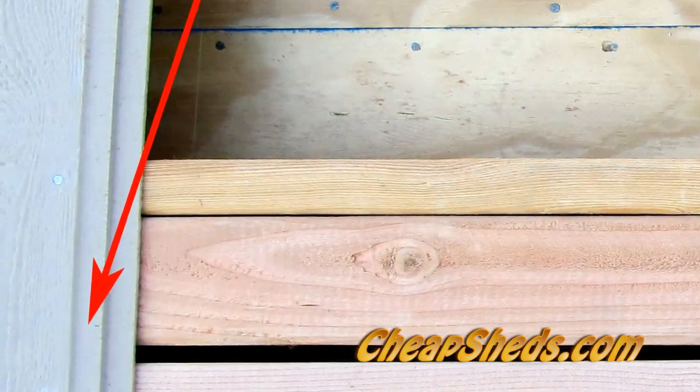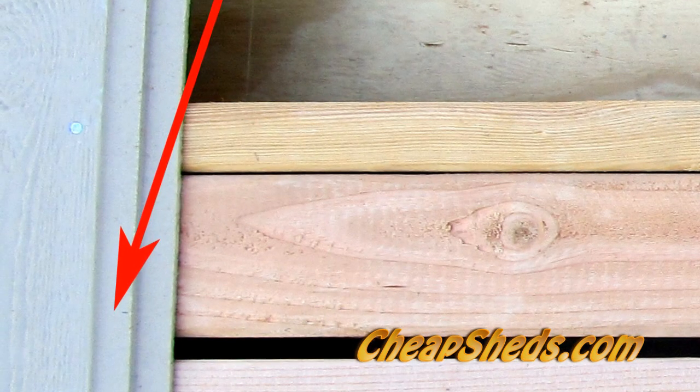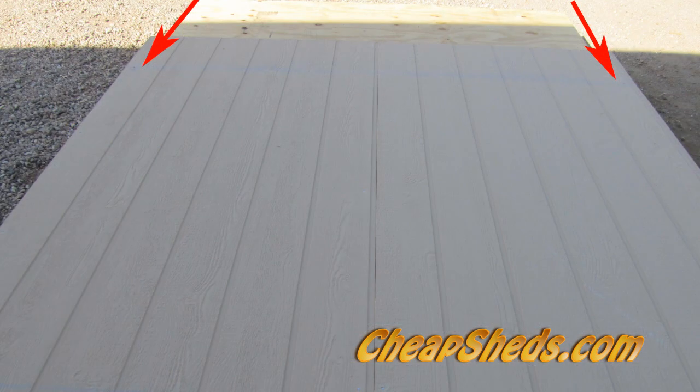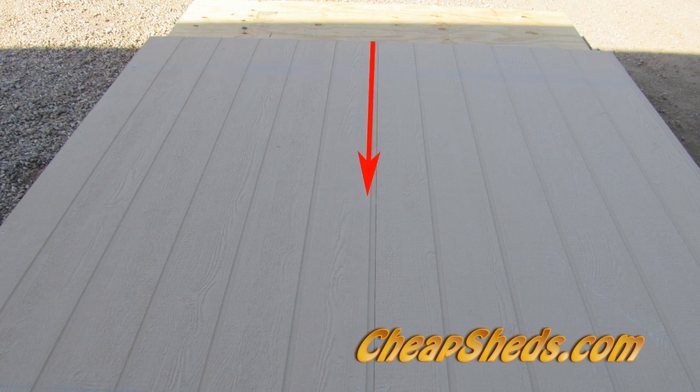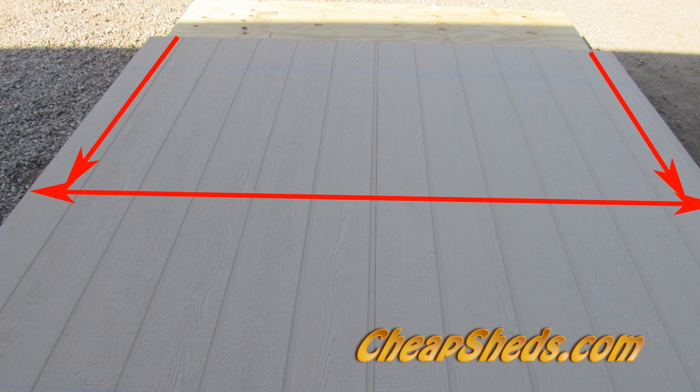Measure from the top of the siding to the mark you made 1/2 inch above the bottom of the door header and transfer this measurement to both ends of the wall and snap a chalk line. This is the horizontal cut line for the top of the door. Measure from the top of the siding to the middle of the door center cross piece as evidenced by the nail heads. Transfer these measurements to both edges of the wall and snap a chalk line. This is also a nail line.